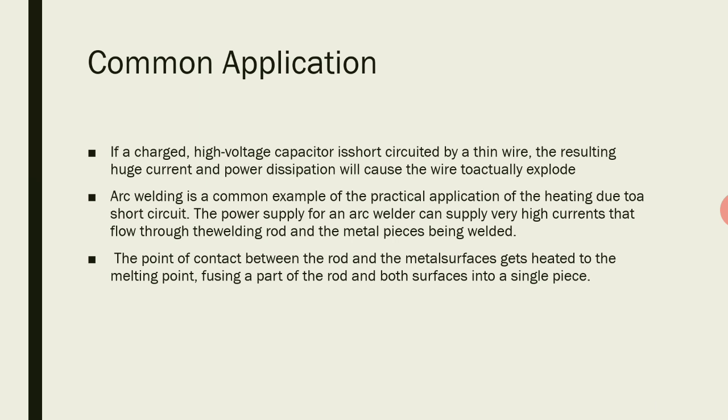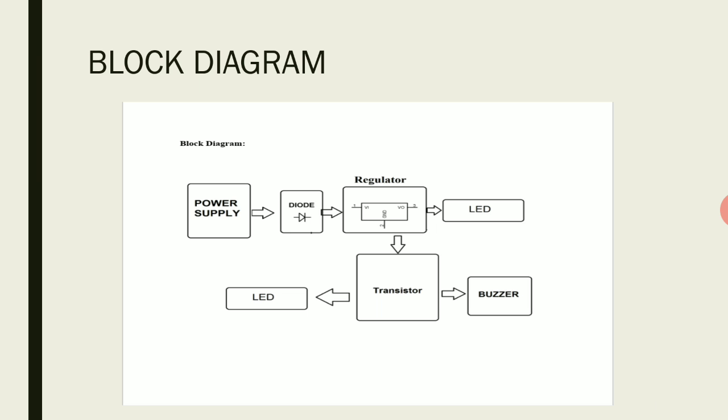Another application of the short circuit is a switch. A switch is an engineered short circuit. When you close the switch, you are actually creating a short circuit between the terminals of the switch. Now let's see the block diagram of a short circuit indicator. It consists of a diode, a regulator, a transistor, a buzzer and two LEDs.